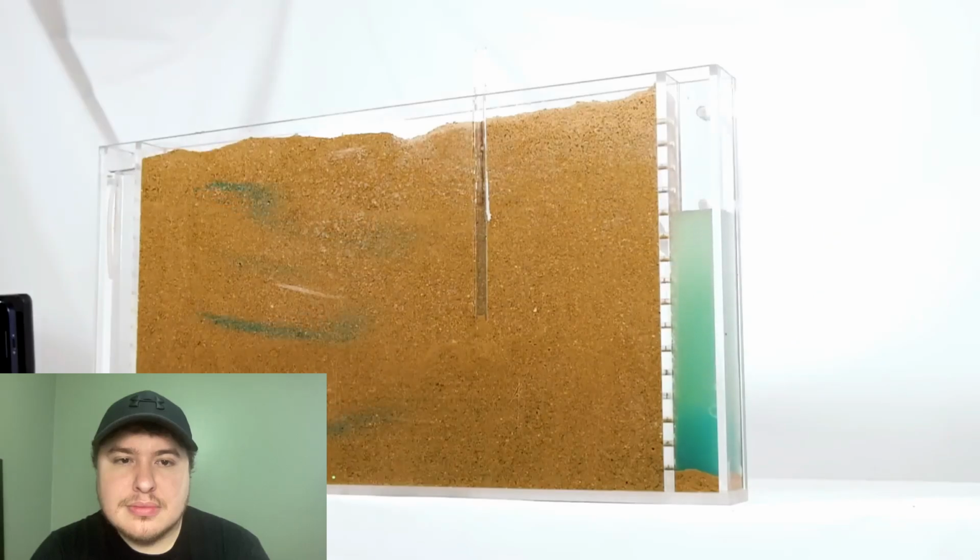I'll be the first to say it, this is not the most mind-blowing revelation. You probably could have predicted it without the fancy model, but to a civil engineer, this is not an inconsequential phenomenon, and for a couple of reasons. First, water seeping below a dam can erode soil particles away, a phenomenon called piping. Obviously, you don't want part of your structure's foundation to be stolen from underneath it, and piping can create a positive feedback loop where failure progresses rapidly. I have a whole video on piping that you can check out after this one.